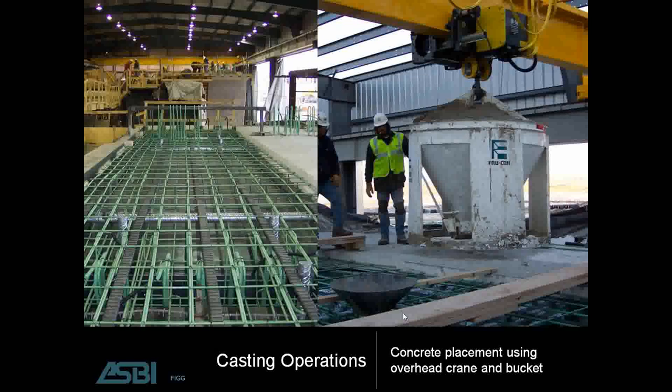And then we have a view inside the casting barn. On the left photo, you see the wet cast. What we call the wet cast is the area where you see the reinforcing, and that's where the concrete will be placed. And the match cast segment is over here on the right, and you'll hear more about this when I get into the presentation. This is a short line method of casting. So the casting machines are inside the shed where they can cast year-round and not be affected by inclement weather. This results in better quality construction.